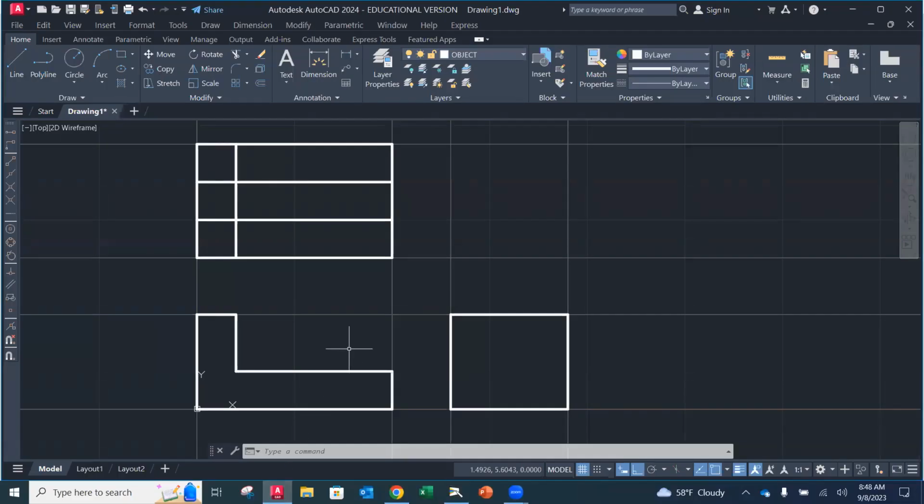So I'm going to go back to AutoCAD here, and I'm going to activate my line command, and it's going to ask me where I want to use my first point. Now, my point is up here, and 0,0 is down here. I would have to figure out exactly where it would be, and you could, but I don't want to. I know where it is starting from that lower right-hand corner of that view, so I'm going to establish a snap from. I'm going to snap from, remember that's my second one down, that corner. And my first line is going to be relative to where that starting point is.